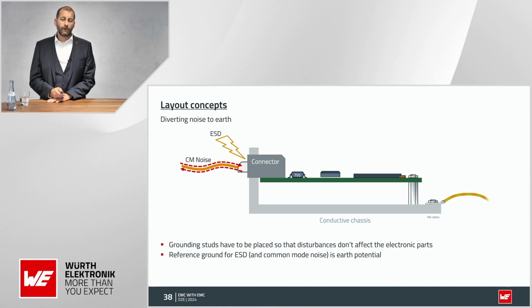But if your ground concept is quite high, going in the direction of high impedance, maybe your ESD is going to ignore your TVS diode and go to your controller. If you add more spacers or better connections, maybe your ESD impulse is going directly over your casing, because that's ideally the least impedance it's going to see.